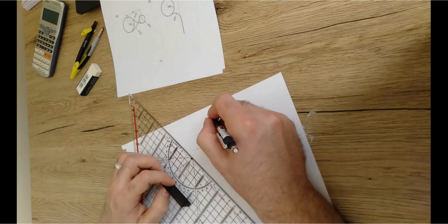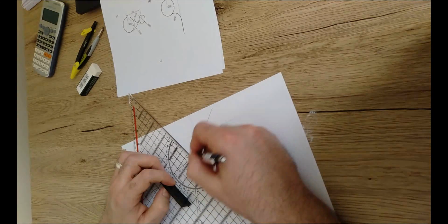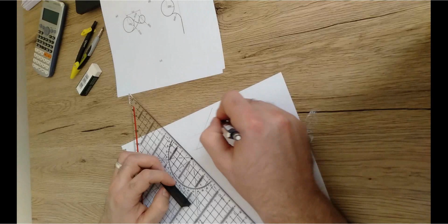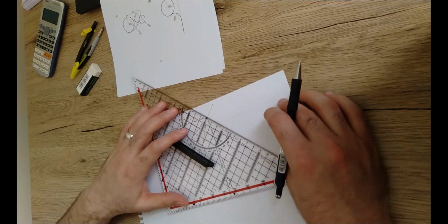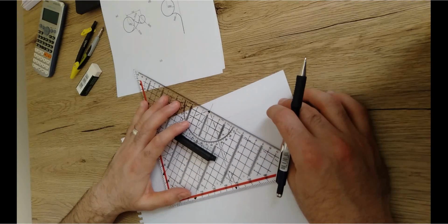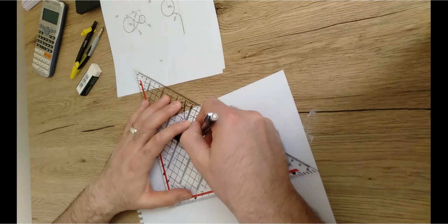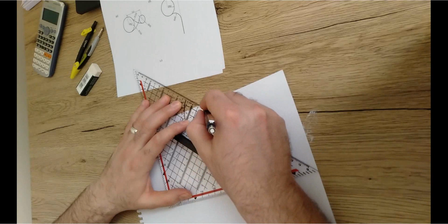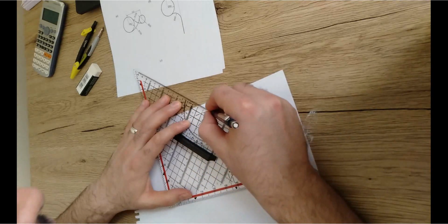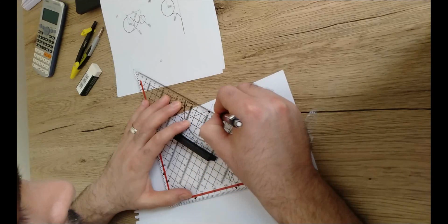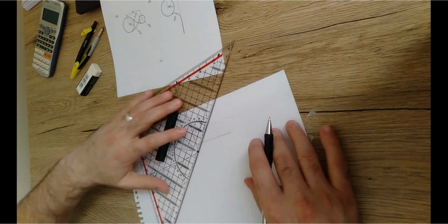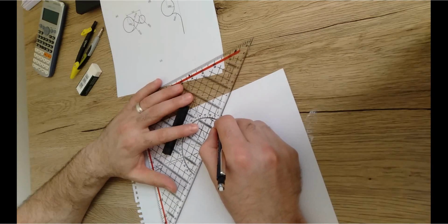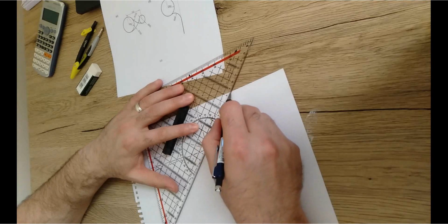Then I'm gonna do the same for this line that is inclined at 45 degrees. So I have to measure 20 millimeters normal, perpendicular. So I have to draw a line first that is perpendicular. This is the line that is considered the black line of the triangle itself. Then you're gonna draw a very light line. Then you're gonna measure 10 and 20. Mark a point. Then from this point, you're just gonna draw a line that is parallel to the original line, and the normal distance definitely is gonna be the 20 that we just measured.